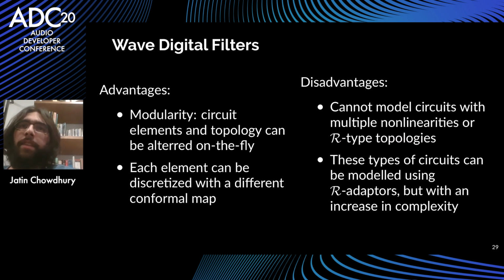So thinking about some of the advantages and disadvantages of WDFs, the big advantage is modularity. So unlike pretty much any other circuit modeling framework, you can swap out your circuit elements and even change your circuit topology on the fly, and the wave digital filter will react in a reasonable and understandable way. So that's really nice and opens up a ton of possibilities for things like modeling circuit bending or doing real-time circuit design and things like that, that are very specific and unique to wave digital filters.